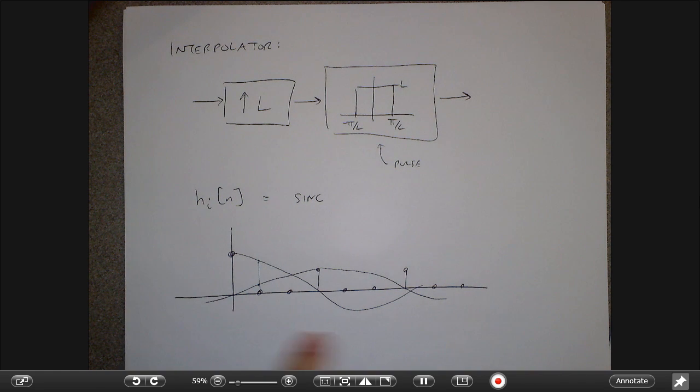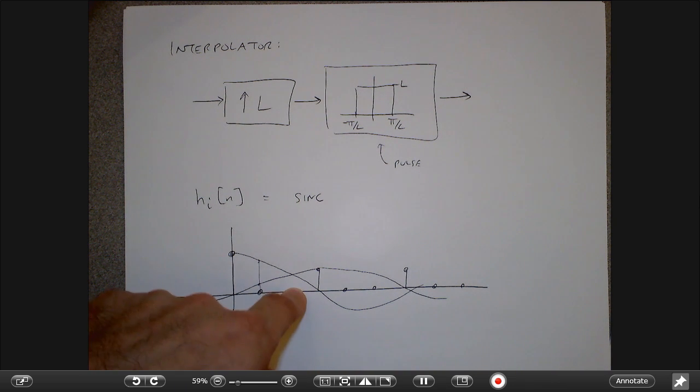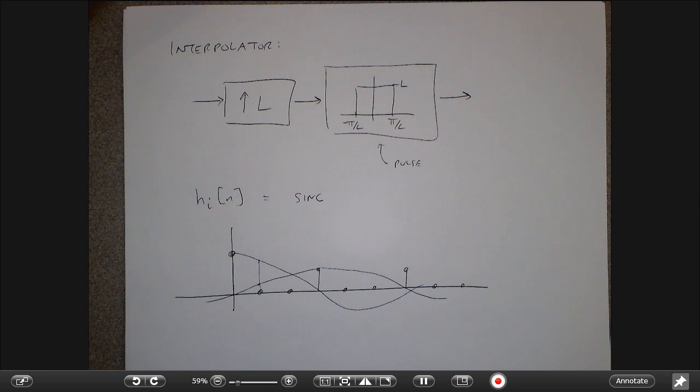Okay, so any questions about upsampling? Yes? Can you reduce the error by using? Well, in some sense, you can never reduce the error beyond the sinc interpolation, because the sinc interpolation is the ideal correct thing, right? If I do this, I get exactly the right samples. You can analyze the error that you get by making a linear interpolation assumption, right?